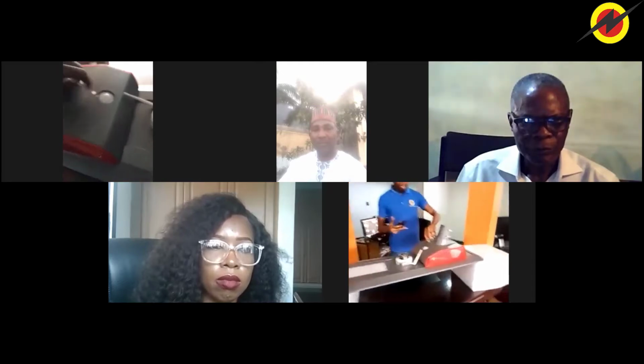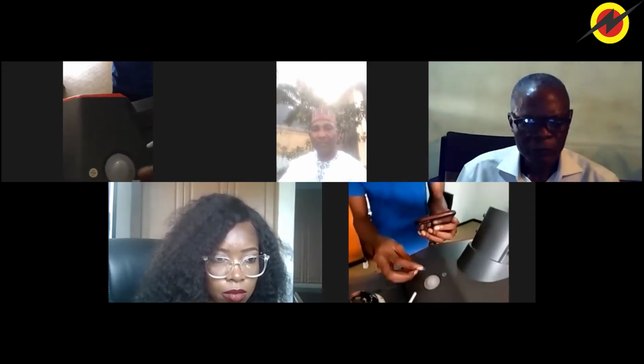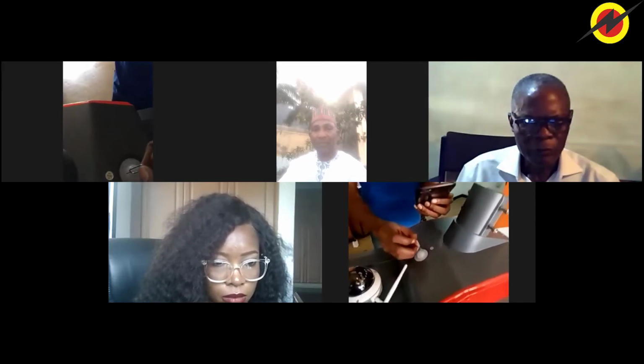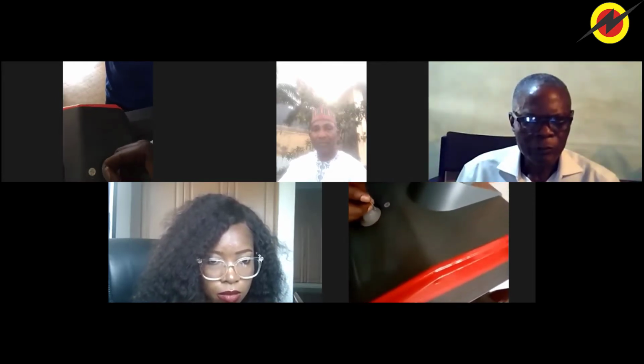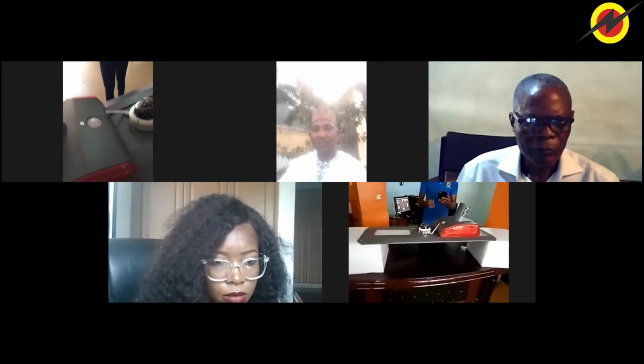Okay, so for starters, the first thing you do, you have to turn on the camera. Since the camera shares the power supply with the street light, there's a button, a motion sensor here. There's a hole just very close by. The light comes with a key. So use that key to press in that hole to turn on the camera. And it's on. Now that powers both the lights and the camera. So once the light comes on, you're very sure the camera is also on. So now the camera is on.